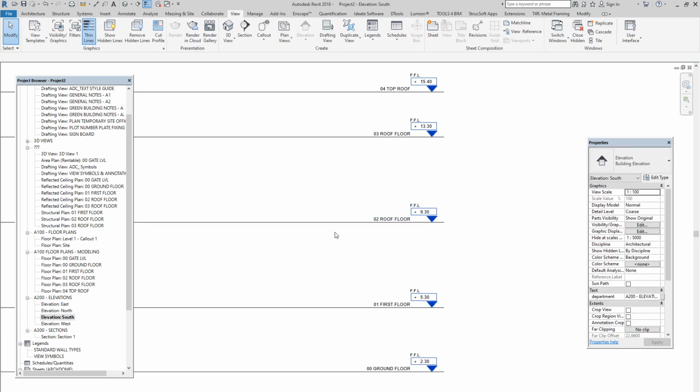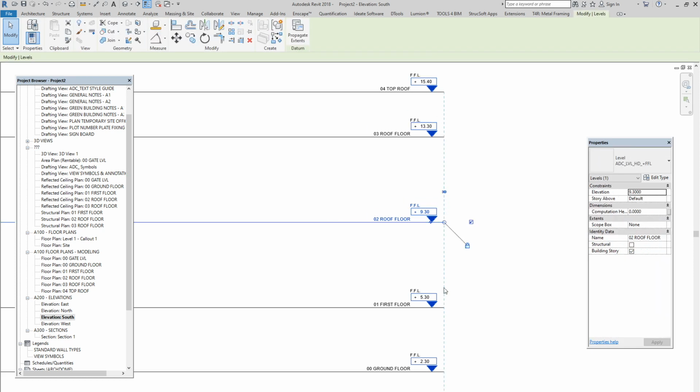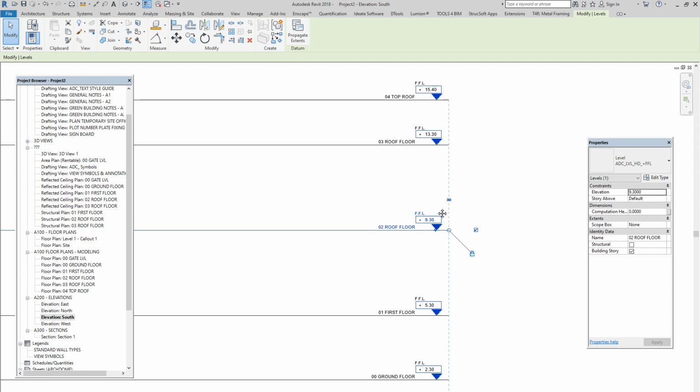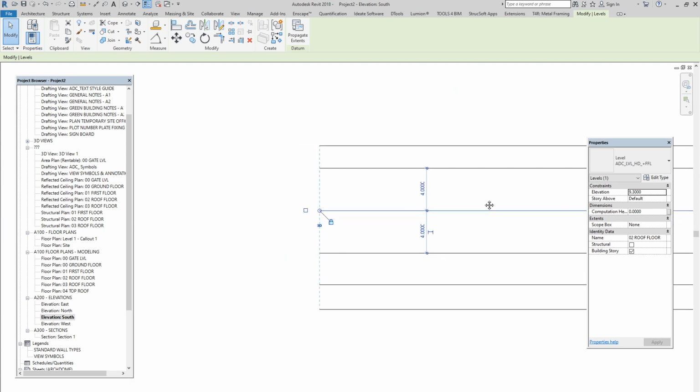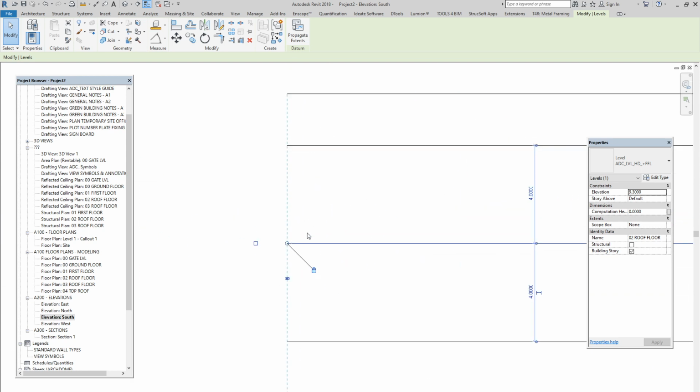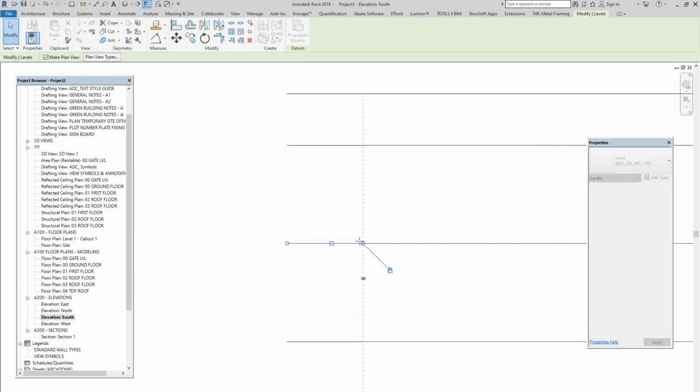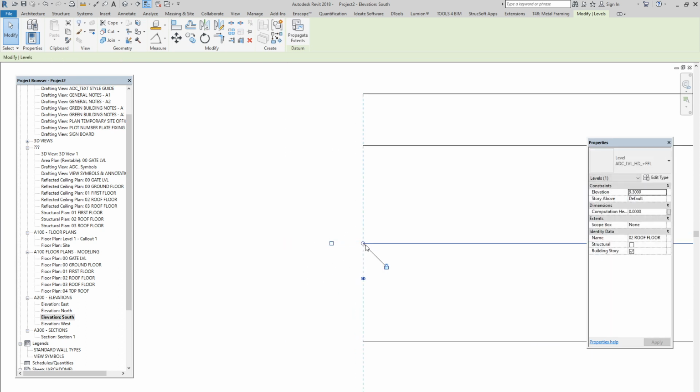Okay, if I select any grid, all of them are already joined together in 3D. I will take it from the other side from here. I will just drag inside, all of the lines will become inside. Suppose for any purpose I need this line to go outside or inside separately, this is also applicable in the grid. Instead of this 3D, just come above this 3D word and one click like that, it will become 2D. If you check now, it will become an isolated point.